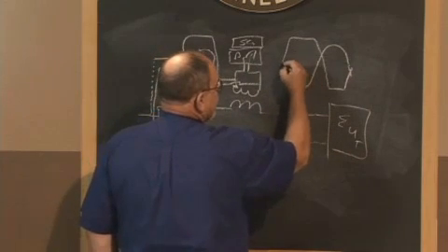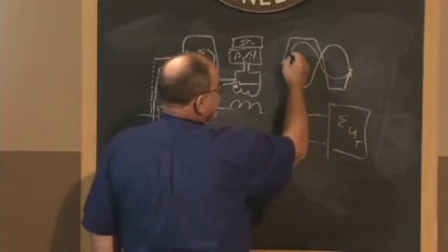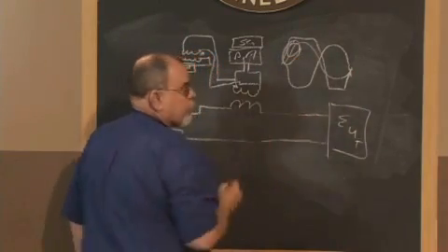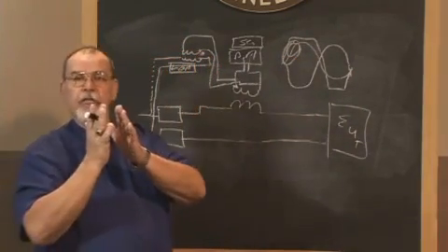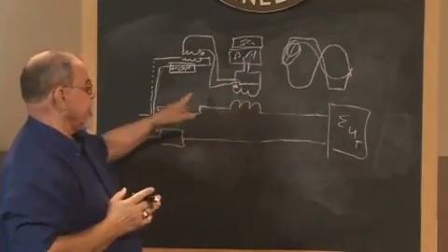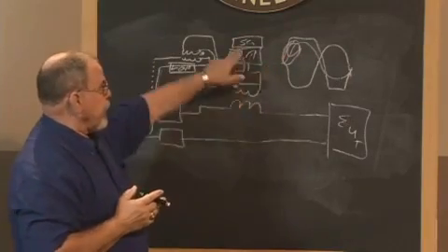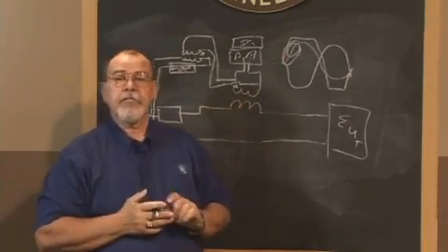So now they don't cancel. I need that waveform to cancel. So all of this area where the distortion causes the waveform not to be sinusoidal presents a current that's not being canceled. If this is excessive, it will cause the power amplifier to trip.